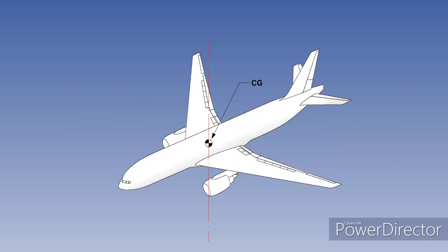One axis runs vertically through the centre of gravity. This is the normal axis, movement about which is controlled by the rudder, the vertical control surface attached to the fin. The movement around the normal axis is called yaw and can be termed directional control. It is worth noting, however, that the rudder is not used to change direction by yawing the aircraft, but rather for preventing yaw, both in normal and asymmetric flight. This will be covered in more detail in a later lesson.